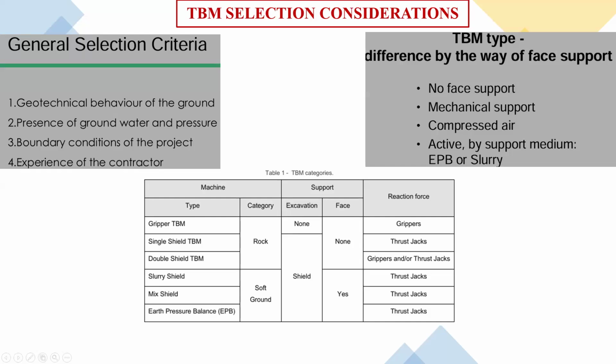If I get a very pure, very hard rock, we work in open mode. If I get some sort of rock and soft ground, we are working in a semi-open mode. If we are getting a very soft ground, then we are working in a full closed mode. So the same machine can switch in 3 modes, either open mode, semi-open mode or closed mode.